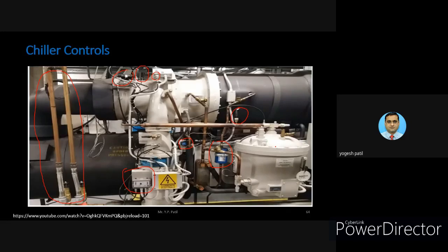Sometimes, because of that, freezing and bursting can happen. The bursting and freezing mainly cause damage to the heat exchanger tubings. The bursting and freezing will damage the tubes of the heat exchangers, because costly tubes are used in these heat exchangers.